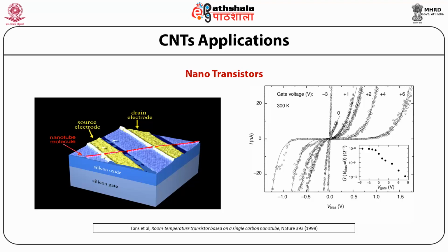Another key contributor to the small scale of the transistor is adoption of end-bonded contact. The metal contacts in transistors have typically been bonded lengthwise along the main body of the transistor semiconductor material, resulting in a long contact along the channel. 2 years ago, IBM demonstrated that this end-bond configuration made it possible to shrink the contact length of an experimental nanotube transistor from 300 nanometer to just 10 nanometer without any increase in the contact resistance.